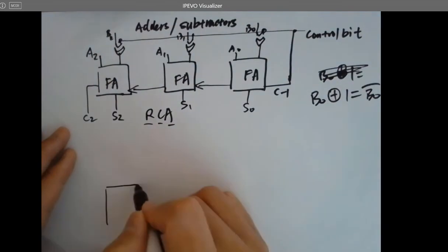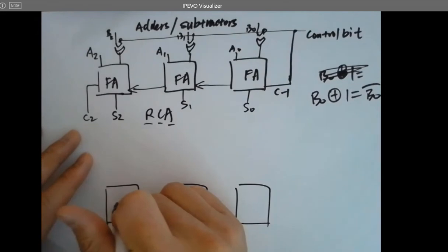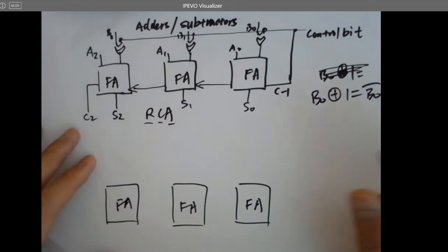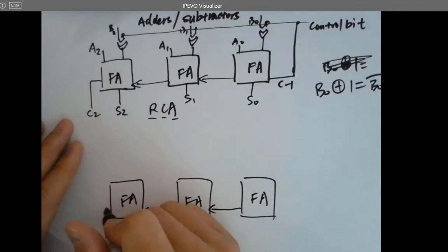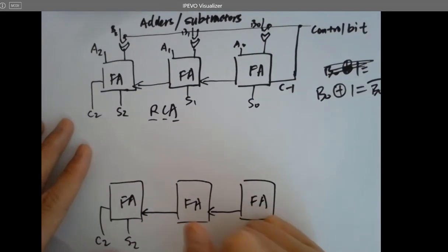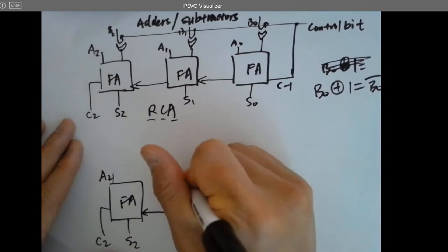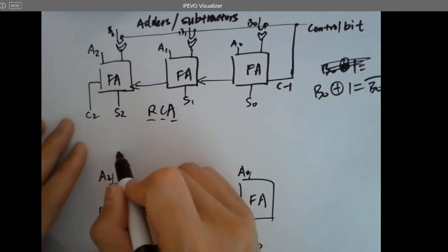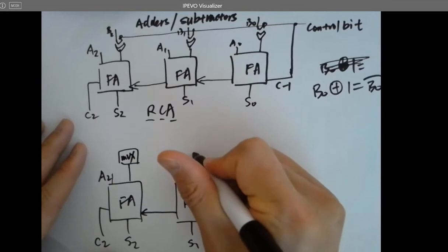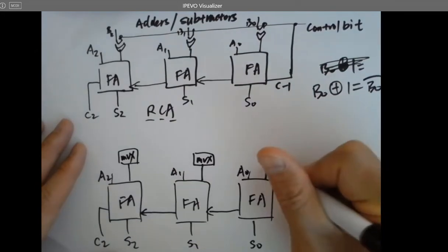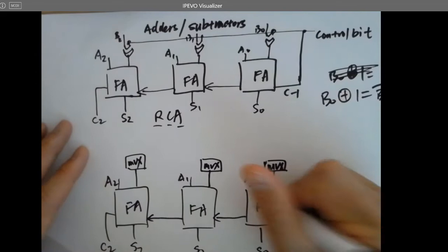And you can also use muxes. Still, the adder can be slow or fast, we're going to talk about it pretty soon, which saves you a lot of space. So I can replace these XOR gates by using muxes. What's the motivation of that? Why do I want to replace it with muxes? You'll see pretty soon. These are smaller.